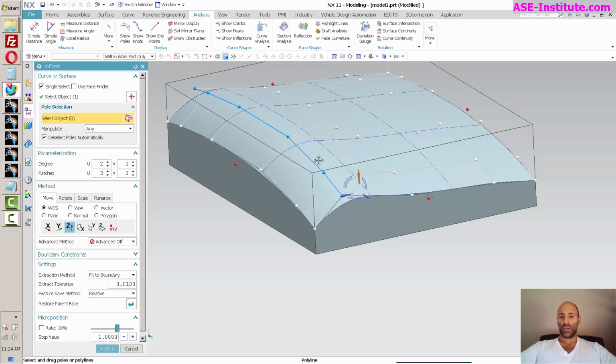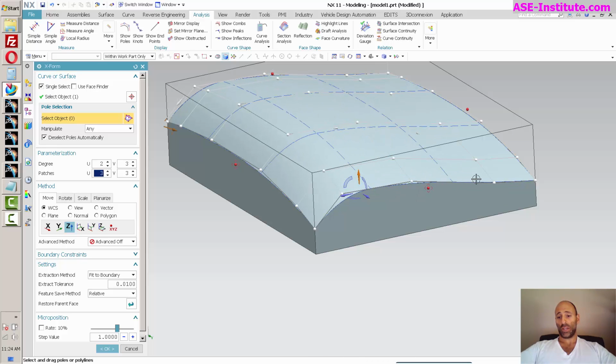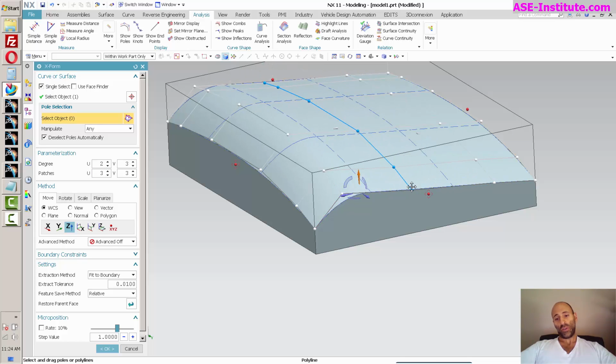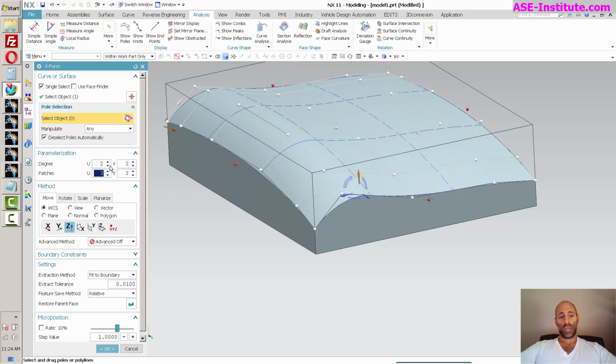Now, if I grab a row interior to that, again, by nature of these control points, you'll see this change does occur further back. But again, it stops at this patch boundary. If I grab this row of control points, it's between these 2 patch boundaries, you'll see that change go beyond each of those patch boundaries. So if you need additional control, you can increase your control points, and you can increase your patches as well.